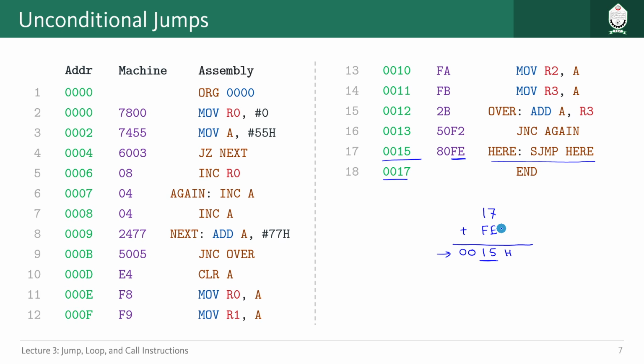So another question can be, in the backward direction, how does it actually work? So you see we have added a value with 17 and we have gotten a lower value somehow, right? I mean, we had a carry or overflow, but we could omit that by the law of binary addition. So finally we got the result which is less than the initial value we had. So how does it actually work? It happens with the help of 2's complement addition and subtraction logic.